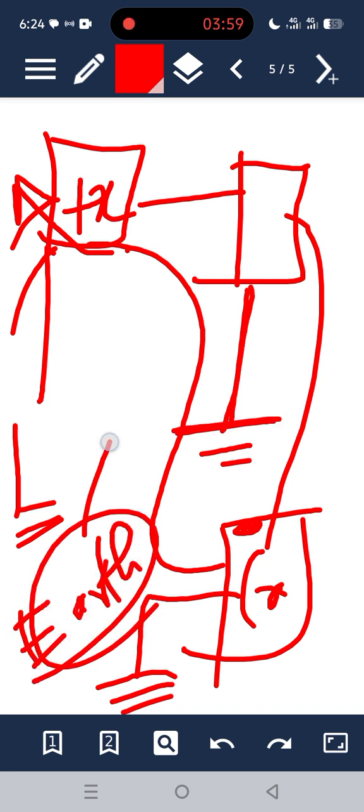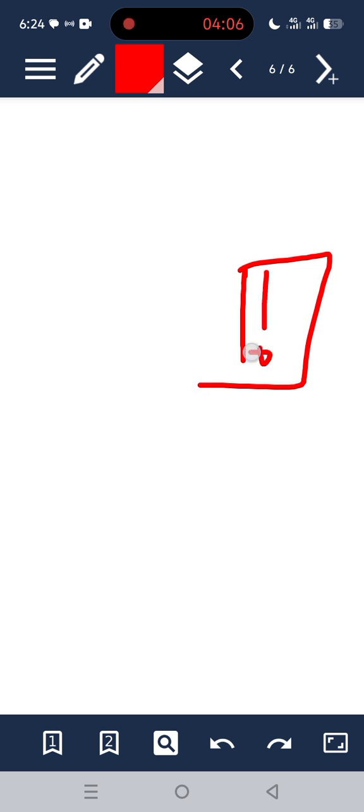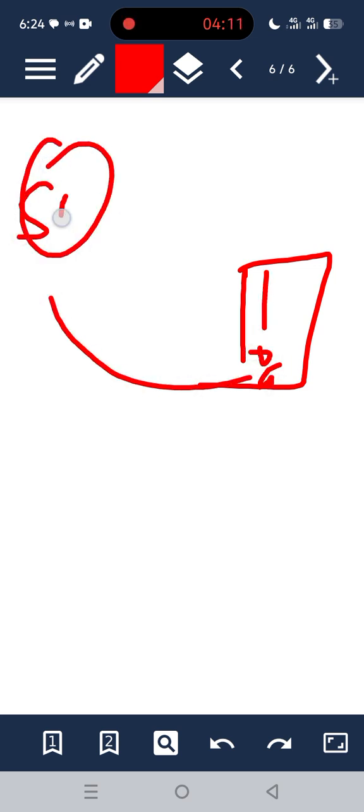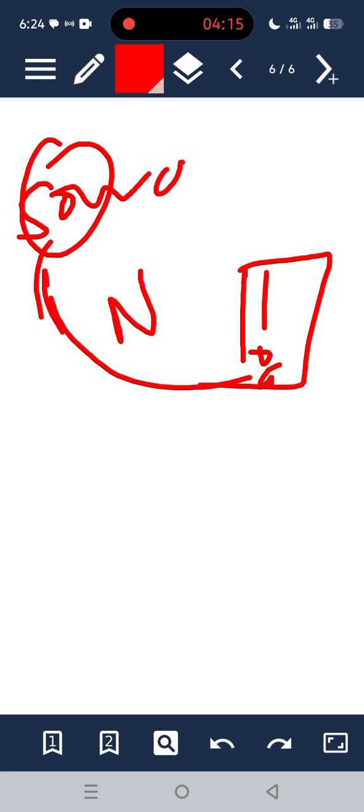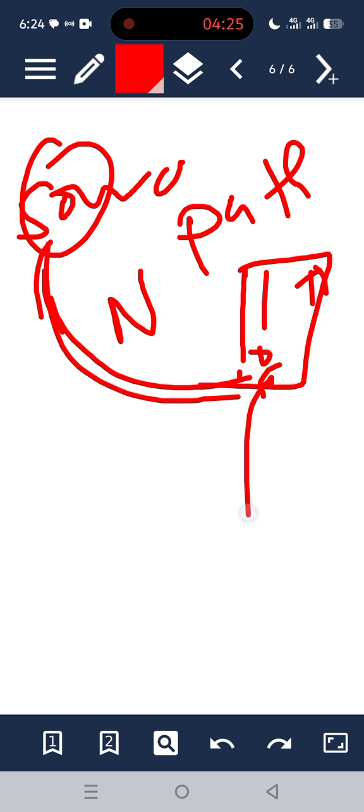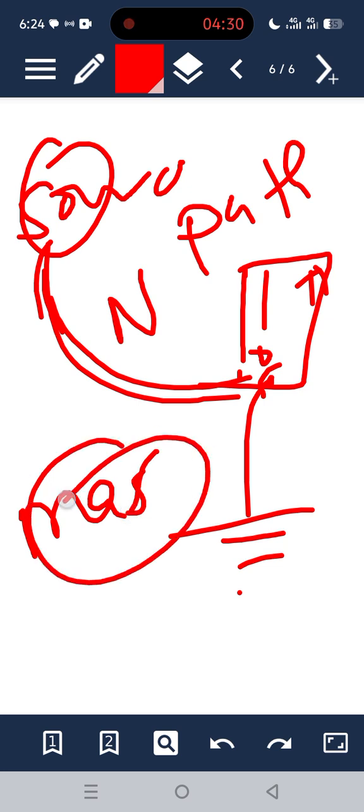So the electricity doesn't just disappear in thin air, rather it travels back from your load to the source, either through the neutral cable so that the path is complete, or, in case there is a fault, it is shared between the load, the neutral, and the earth wire, and the earth mass serves as the return to the source.